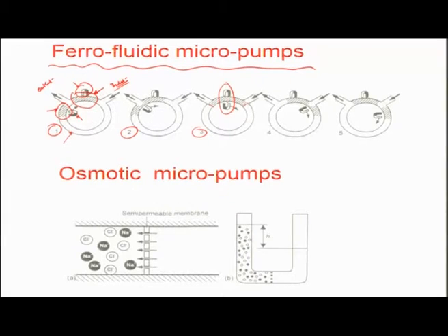Okay, and from here, when the motion starts, the core magnet again starts going in a clockwise direction. It starts separating one portion as a plug along with it, which it drags along as this magnet moves. This plug also moves, and because the plug moves, there is a pressure difference created here in which the inlet water can be fed in.